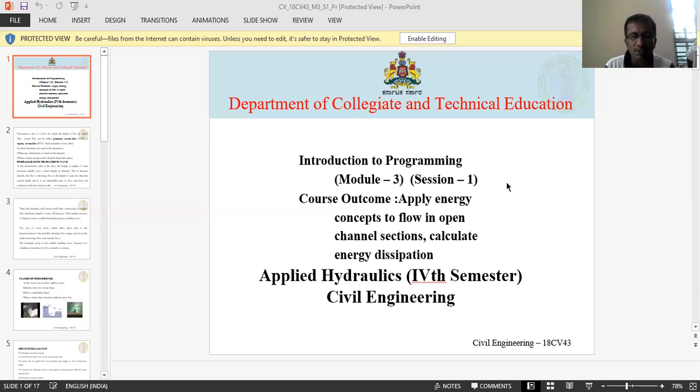Unless you are familiar with specific energy, and the relationship between specific energy, depth of flow and critical depth of flow, it is somewhat difficult to understand them. yc stands for critical depth of flow, Ec stands for critical specific energy. Other than at Ec and yc, you get two depths of flow as well as two specific energies.